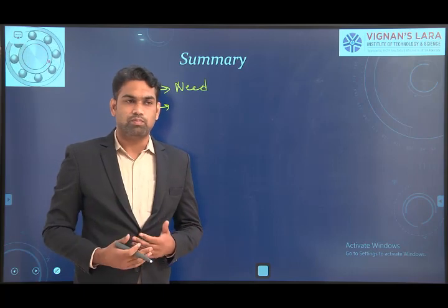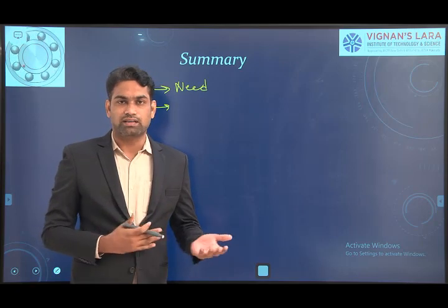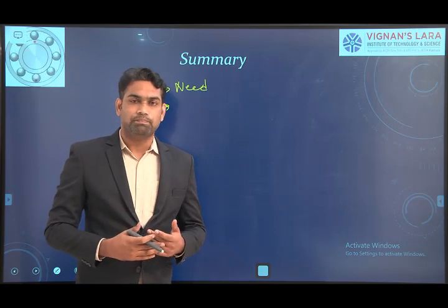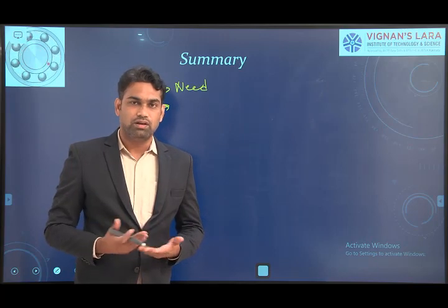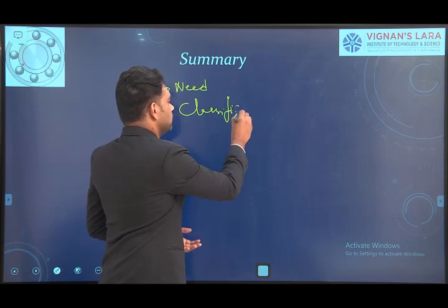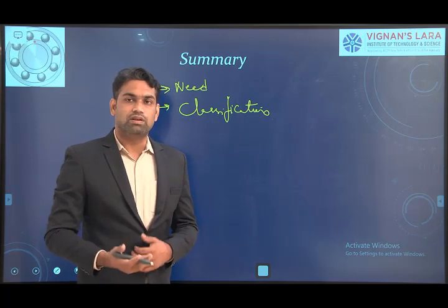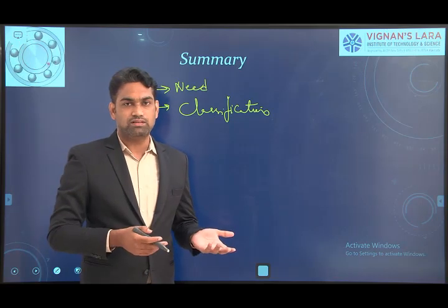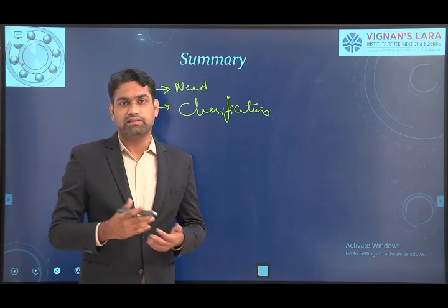It is going to support, it will allow the relative motion, and it will constrain the motion with respect to another. We also need to provide better lubrication to reduce friction, wear, and corrosion. And you can see the broad classification of bearings based upon the type of load conditions it can support and the nature of contact between the two surfaces: radial bearings and axial bearings, that is thrust bearings. In nature of contact, it may be sliding contact bearings and rolling contact bearings.